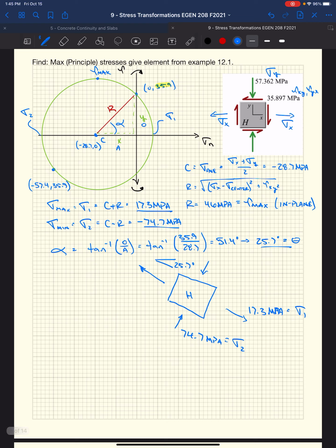And in some cases, say it was an existing flagpole and we added additional load and we had to maybe retrofit it, we could look at that and maybe you add in a spiral band of, say, reinforcement plates or something like that, right? To counteract the stresses at that angle. Maybe you wrap it in fiberglass or glass fiber reinforced polymer or something like that in order to strengthen it. All this making sense? We're going to keep going through a bunch more examples because this is a big part of this class, okay?